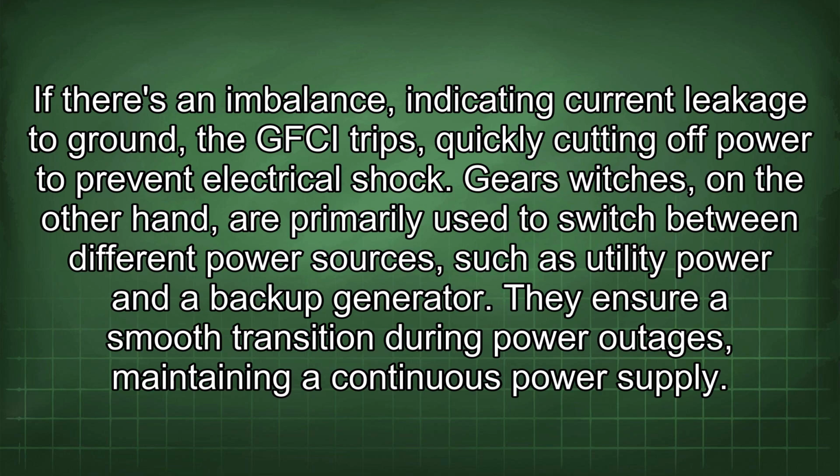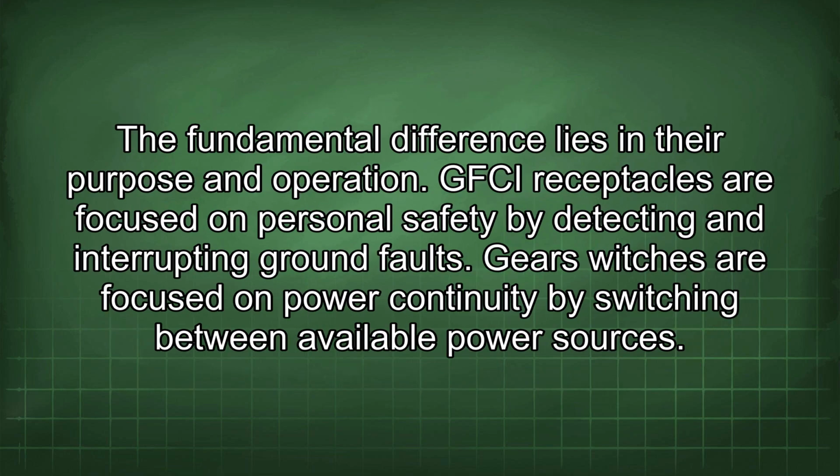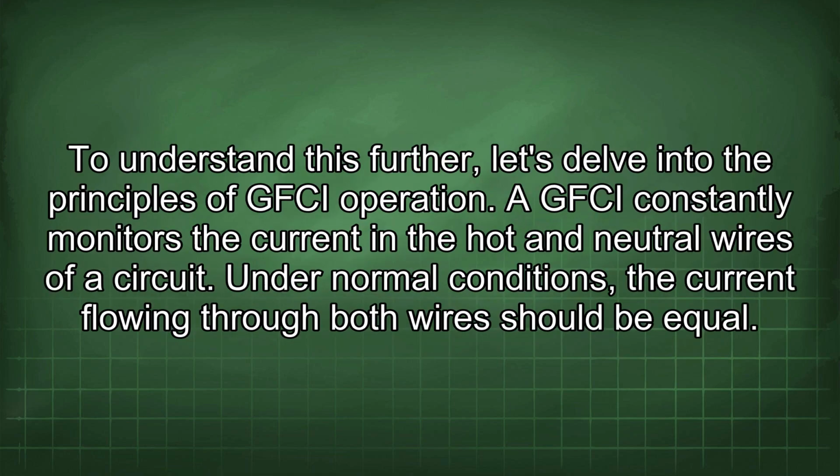They ensure a smooth transition during power outages, maintaining a continuous power supply. The fundamental difference lies in their purpose and operation. GFCI receptacles are focused on personal safety by detecting and interrupting ground faults. Transfer switches are focused on power continuity by switching between available power sources. To understand this further, let's delve into the principles of GFCI operation.